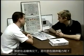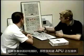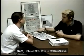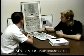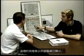So what's supplying the electrical power in this case? If I see avail and avail, then I know that the APU is supplying power, because the on light down here just means that the APU is starting, so it should be out. The on light up here indicates that the external power is on.